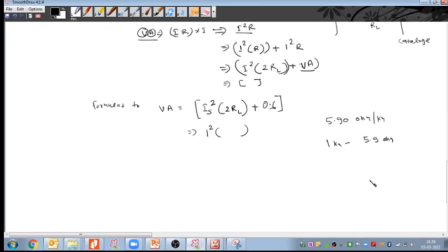And let us take 500 meter, for example. For that we need to check the distance between the CT and the panel energy meters. Generally, suppose the length is not clear at the starting stage, in that case we generally take 500 meters. I am telling this tentative value, but when you are making the electrical layout, in that case we have to measure this value by AutoCAD.